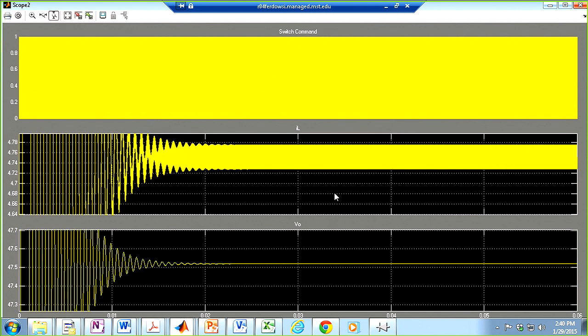This is because I've chosen L to be much larger than the critical expression, no matter how D varies. If L is very close to the critical value, then the value of the duty cycle will have an impact. Otherwise, it did not significantly change anything. In practice, you are trying to avoid Ds that are too small or too large, and here is the reason.